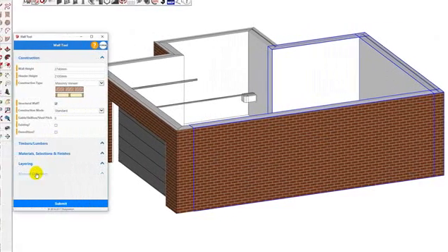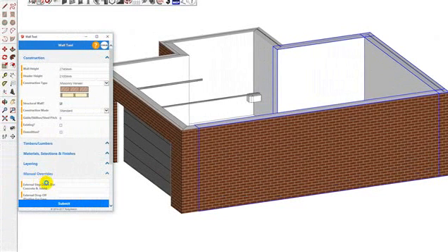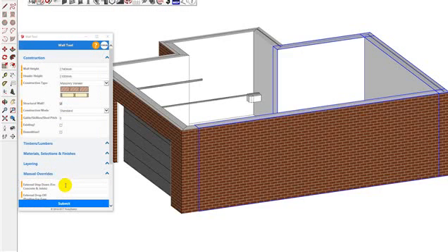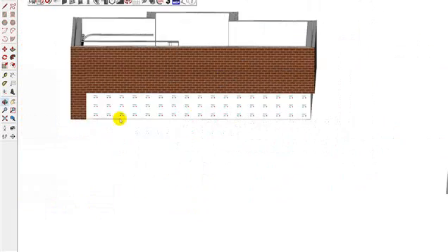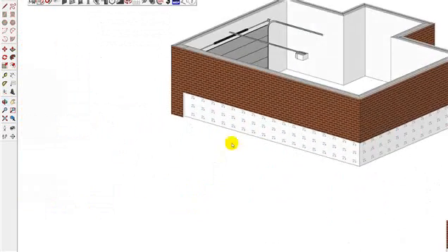Okay, so down the bottom of manual overrides, you've got external step down for concrete and joists, right? Now it needs to be minus. So say it was up a meter. I go minus 1 meter, right? And I go submit. Right, see what happened? And now my retaining wall would now go in here.